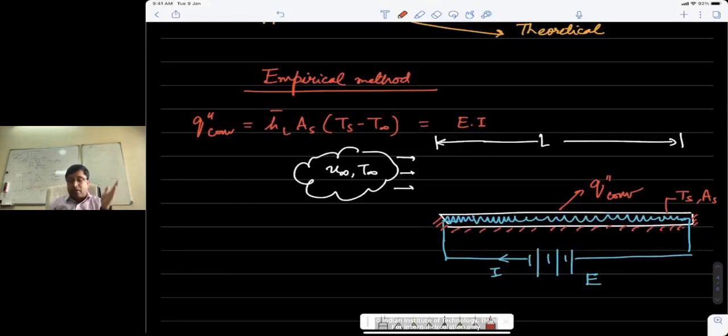When the fluid changes, for instance, if I choose air, air has a Prandtl number of about 0.7, but if you choose water, the Prandtl number increases. So you can actually do this experiment for a range of fluids, and so you have data for each and every fluid. Moreover, you can change the velocity u infinity.